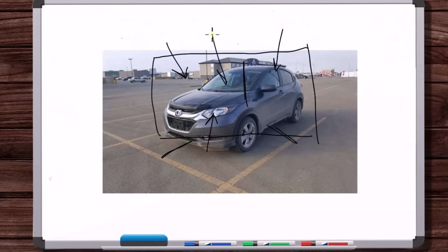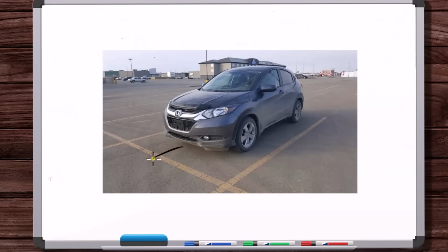And we had all kinds of forces in this plane, and that was the only forces on the vehicle, and maybe even a couple moment with the axis perpendicular to the plane. So yes, we could use the coplanar force special case to reduce all of these forces down to a single force in that plane. And we could also get rid of the couple moment for the coplanar case, just a single force. But okay, let me put the coordinate axes back here.